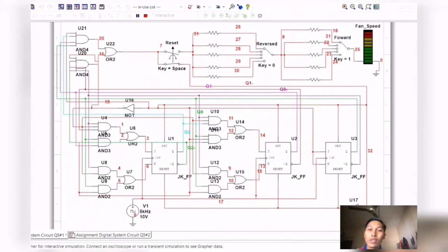The circuit that we designed is from the result of the Karnaugh map, where we obtain the input and output states from the truth table before. The circuit uses 3 JK flip-flops, which means it has 8 states, but the question only asks for 5 states. The right side JK flip-flop is called the least significant bit, while the left side JK flip-flop is called the most significant bit. The logic gate connections are based on the result that we got from the K-map.